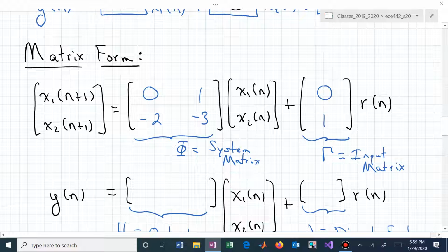On your homework, you actually have a 2 output system in, I don't know, problem 3 maybe. Is that the state space problem? In problem 3 of homework 1, how many state variables do you expect to have? I hope people have looked at it. How many energy storage elements are there? There are 4. There's 2 inductors and 2 capacitors. You're expecting a 4th order state space representation.